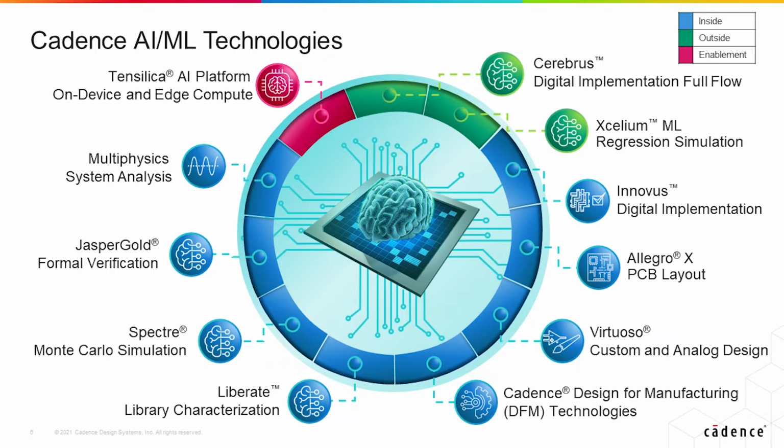Allegro X. Allegro X leverages an ML-based engine for synthesis of a PCB from its specifications based on constraints provided. The place and route of PCB is for the first time being assisted in automation by ML techniques. Blended into the Allegro X platform, one can initiate the design in the canvas familiar to the user and then leverage the engine to explore multiple implementation alternatives, and then finish the design for manufacturing in Allegro X design environment.